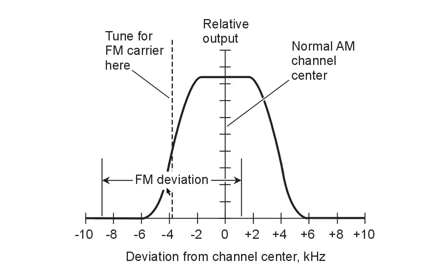Now actually, a typical FM signal plus or minus 5 kilohertz would make excursions into the nonlinear part of this response curve, so that slope detection is going to give us, in many instances, a good deal of audio distortion in the output. But we can, in theory, demodulate an FM signal this way. I just thought that I would show you this illustration because it's just kind of a cool technique, even though it's cheating a little bit.